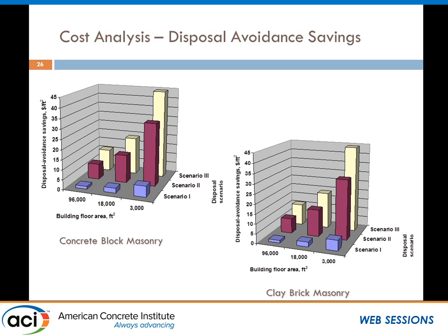But scenario 2, which is much tougher because you have to dump it in a secure landfill, our saving could be up to like $30 per square feet in a smaller size building, and for a normal, big-size building it could be like $10 per square feet. That's quite a lot of saving. And scenario 3 is to remove the surface lead-based paint, and then put the remainder into a landfill. And you can see the saving could be close to $45 per square feet. We're showing all the 4 different kinds of aggregates used here. Again, these are our major findings.